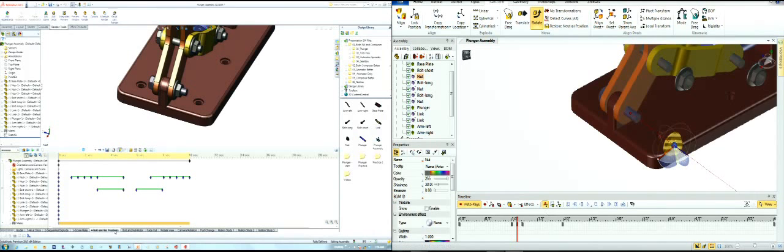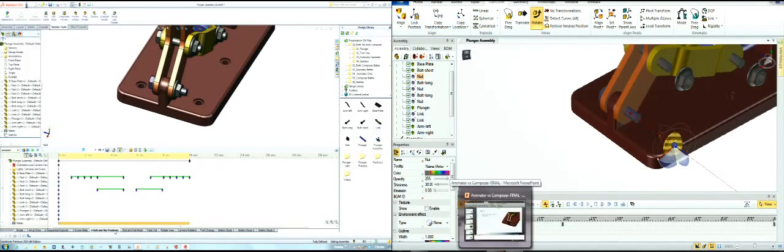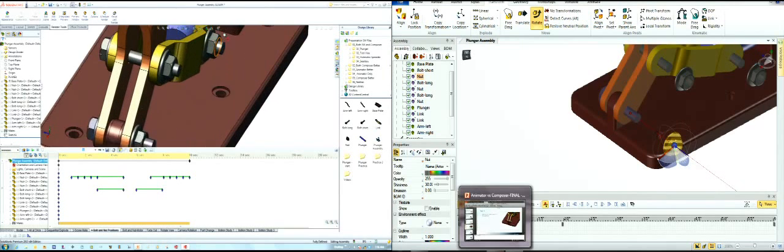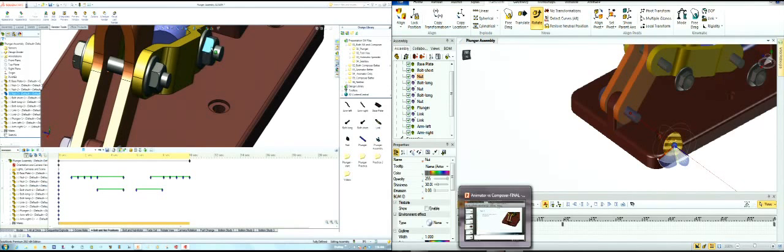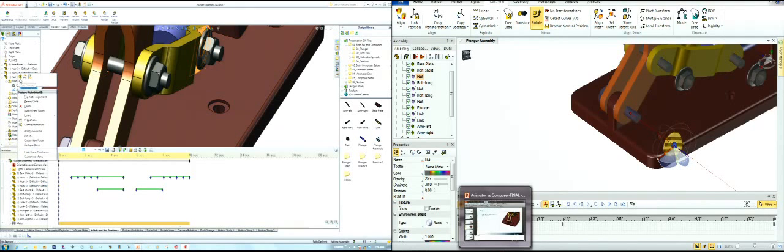Okay, on the SolidWorks side, there's about 4 ways to do this. The first basic way is very similar to what Callie did, but she didn't mention one other thing that she can do, which I'll tell you in just a second, that makes the job a little bit easier. So I need to make sure this nut is not tied in here. And you notice, because I mentioned earlier, we got mates, so we want to make sure that this coincident mate is suppressed, because if it's not suppressed, this thing can't move.